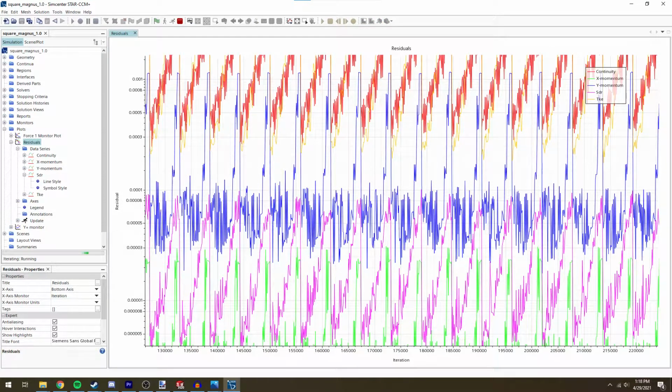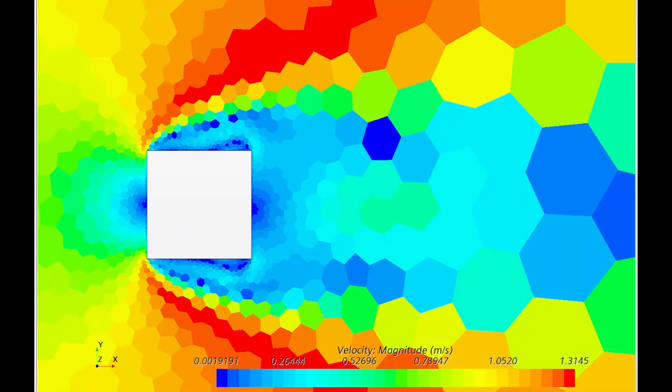For the results of the simulations to be accurate, it was essential that the models were structured to be iteratively solved for a transient solution of the Magnus effect. Earlier trials of steady-state solutions were not indicative of real-world effects and often would fail to model the Magnus effect in any capacity. The transient solutions, while computationally intensive, proved to be the best option to reflect physical validity.